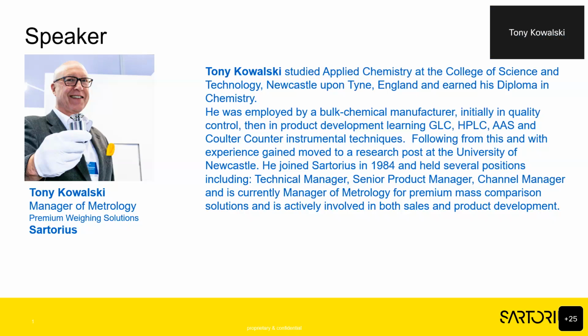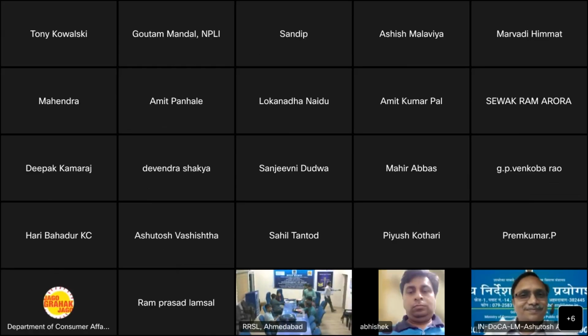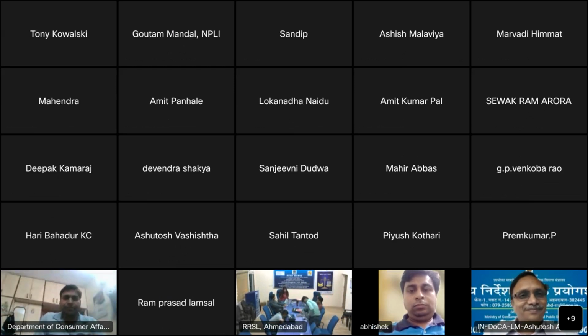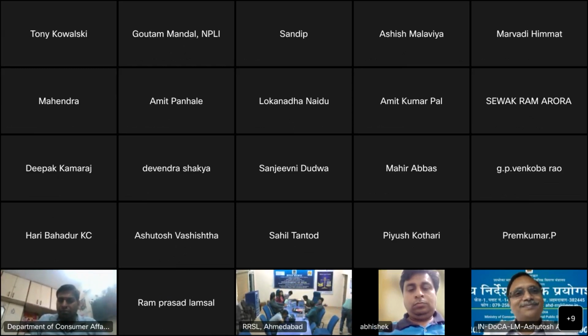And every time he failed on the uncertainty contribution in the weighing process, simply because if you use the same quality reference and test weights, the contribution from the testing weight and the reference weight is just too high. You must always have one class higher. And I know it's difficult with E1 to find, maybe NPL would be the only people to give you an E0 type weight calibration.